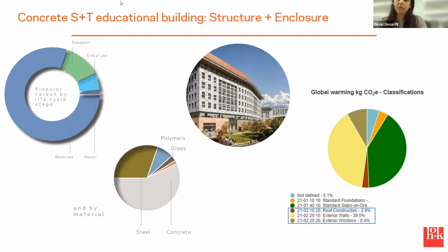Sometimes that's really obvious. For example, if we're designing an office building and we're putting it in a corporate park where all of the other buildings are tilt-up concrete, that's very clearly the baseline. So we would do some quick calculations to see what the bill of materials would be if we had designed the baseline building, and we compare it to what we actually did, which might be composite steel with curtain wall or some sort of masonry facade.